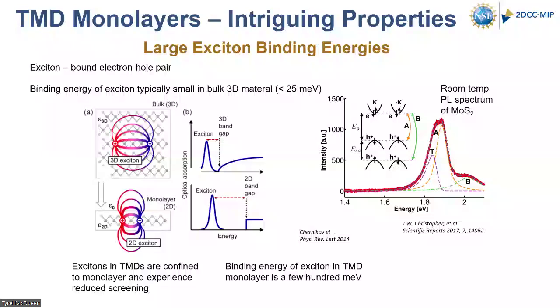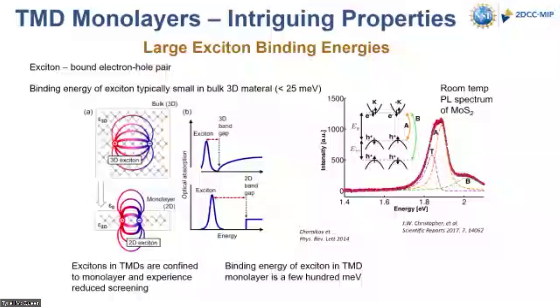And so as a result, at room temperature, we typically don't see a lot of absorption or light emission due to excitons, right? It's usually band to band or defect to band, right? But now, whenever we shrink down these layers to a single monolayer, the electric field lines of the electron-hole pair extend beyond the physical thickness of the 2D layer.